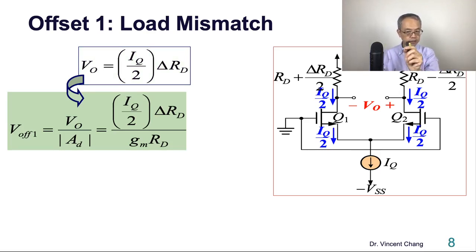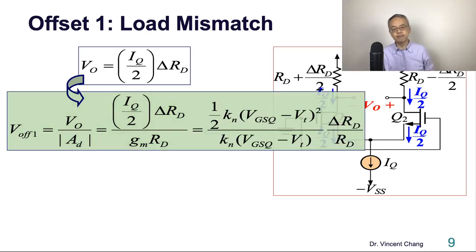I also skipped explaining the origin of finding the differential gain, the gM. I assume you are very familiar with this. And then what? Transconductance of the MOS transistor. So maybe just pause. Put down the square law relationship: ID equals half Kn (VGS minus VT) squared. What T? Not thermal, threshold, the threshold voltage. Partial ID over partial VGS, the derivative, so Kn (VGS minus VT). I hope you can follow me. And also half IQ in terms of VGSQ is the square law.